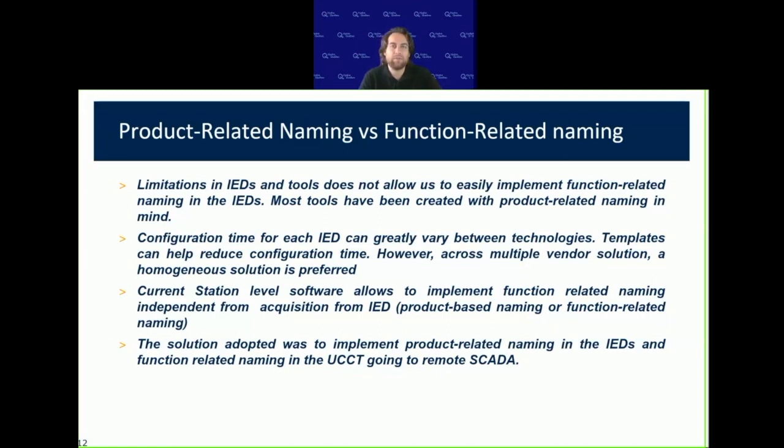Most of them have been designed with more product-related naming, as that was the standard engineering process used before the coming of 61850. So we faced some issues in some of the IED technologies, and it was greatly increasing the configuration time in the IEDs if we wanted to go ahead with the function-related naming.